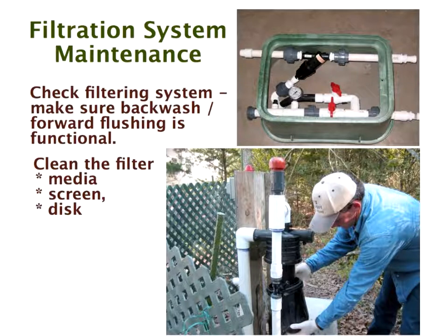Here again, you take that apart, you disconnect it here. It's an easy disconnect. You can disconnect it there, and you can take the whole filter out and clean it, or you can get the screen out and the disc out. The same here, he's taking out the bottom. The bottom there is being screwed off, and that is a disc filter in there. And here you notice he's got an air vacuum relief valve at the top. He's unscrewing it, and you've got to take it out, separate the discs and clean them.